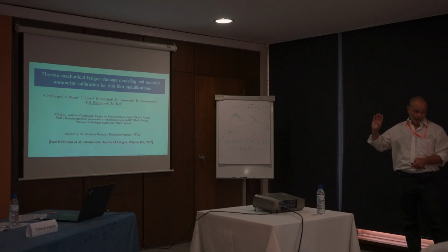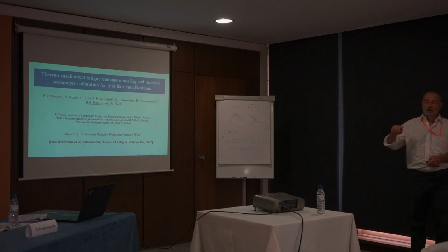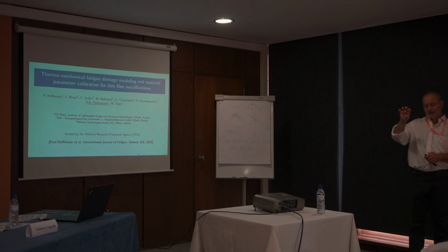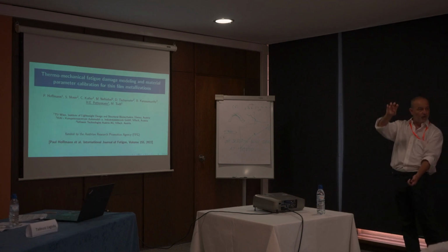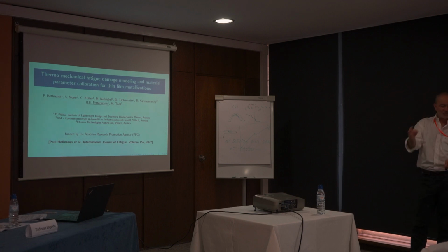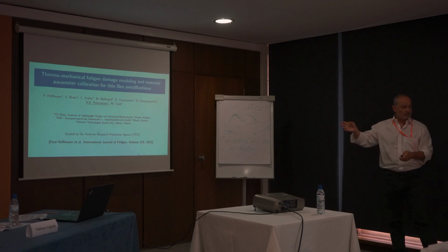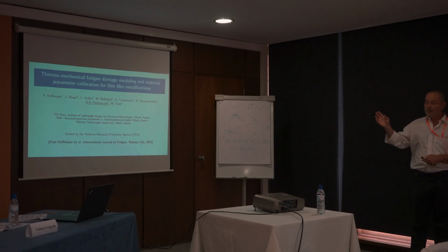So the FEM model is a plane strain model. We do not have a gradient in the thickness direction in the geometry, and the part which gets hot is very small compared to the entire thickness of the silicon. So the better part of the silicon just stays cold and restrains the strain in our region of interest. So that's the reason why we use plane strain.